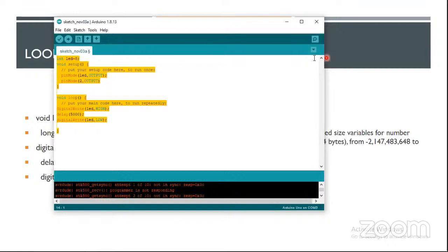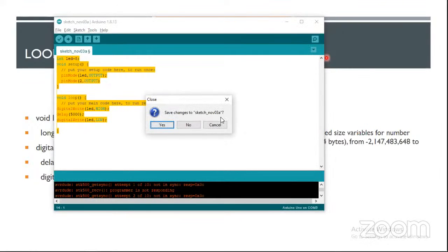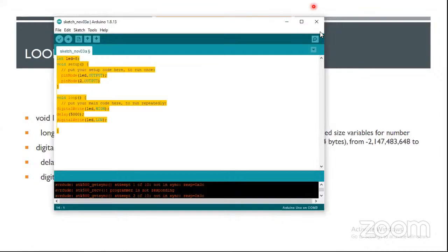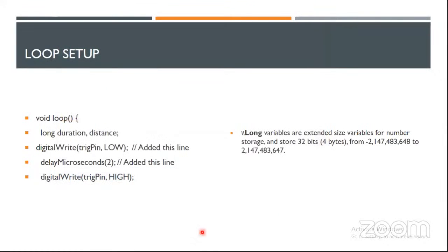The next thing here is the concept of selecting the sensor. When you are selecting the sensor, we first need to know your requirement. If you want to make an automatic door open and close, we need to select a motion detector sensor. For car parking, we need an ultrasonic sensor, for temperature we need a temperature sensor, and for light variance we need the LDR. So this kind of thing we always need to think about. Based on your requirements, we need to research what kind of sensor will help us.